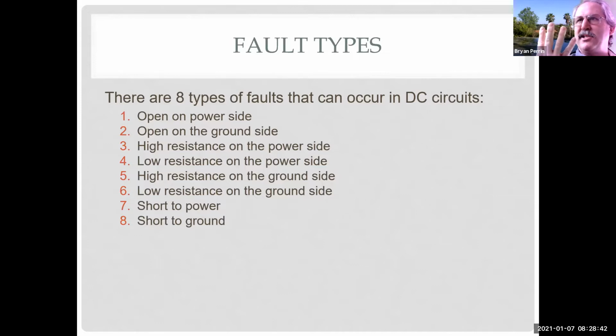So doesn't it make sense to think about how things fault and how to diagnose those faults? And then if I read a wiring schematic, look at how the circuit's built, figure out what volts I should have at a particular test point, go use my tools to test for that. And based on those results, I can decide which of those 4 faults I have and then diagnose it. So it really tends to compartmentalize things.